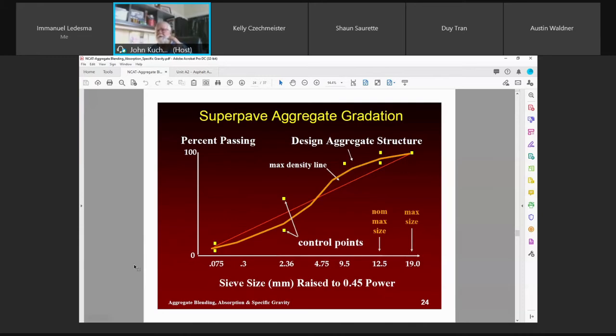They're not taking into consideration the asphalt cement during service life, which you have to design for. And essentially that's what they do. Plus it's a different way of compaction. Superpave, put it in a mold just like we do with Marshall, but with Marshall we put a hammer in it and we drop it, almost like a Proctor hammer, okay? Except it's a Marshall hammer, it's heavier. And you're compacting it in a mold by dropping a hammer, like a Proctor.